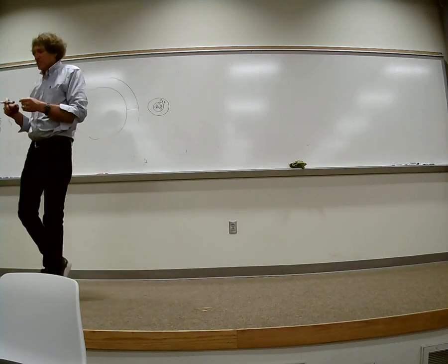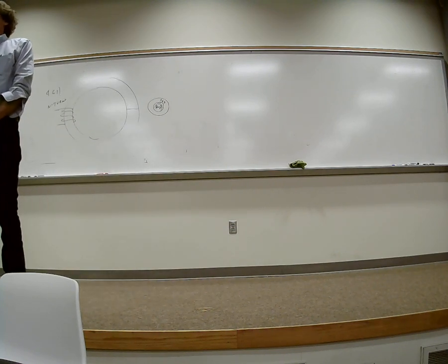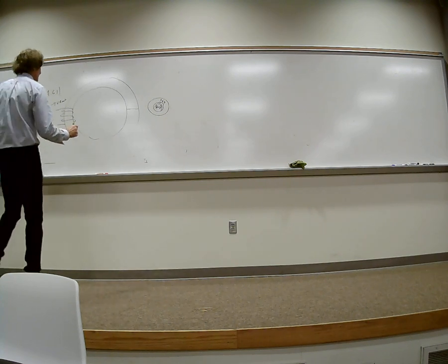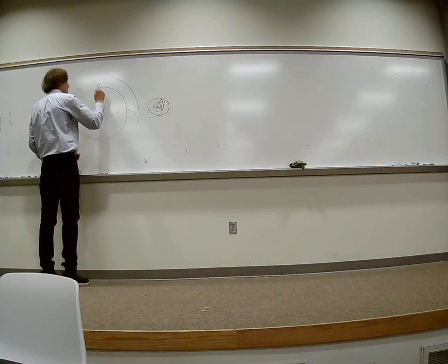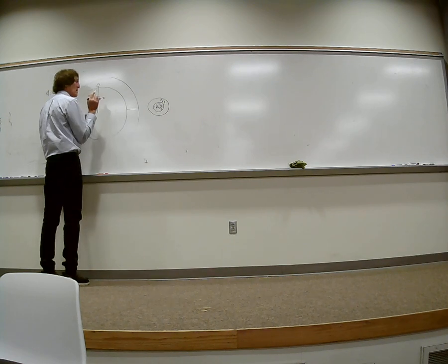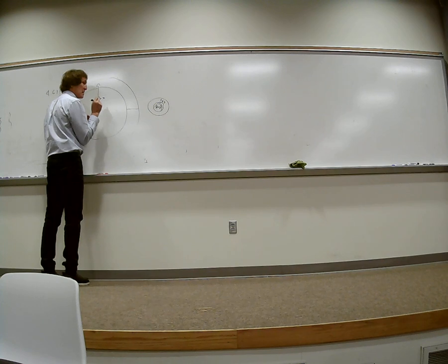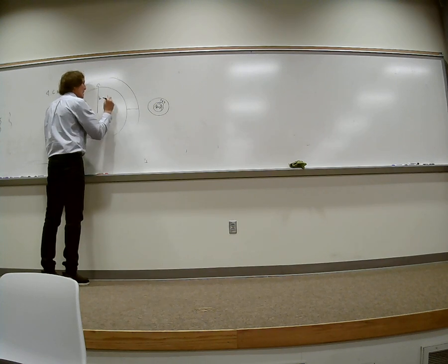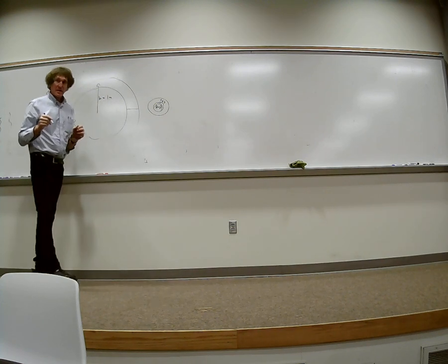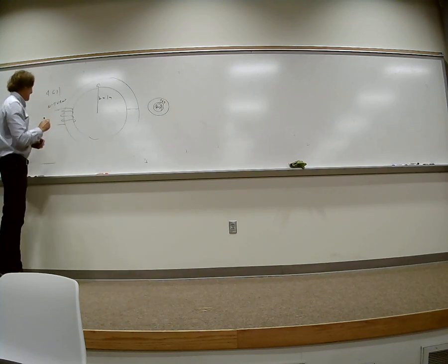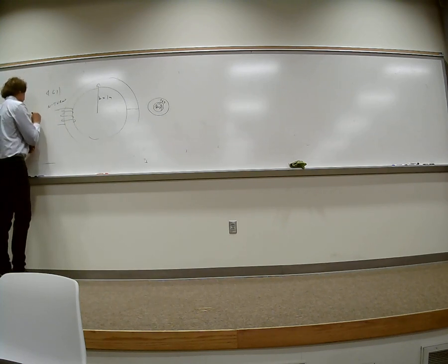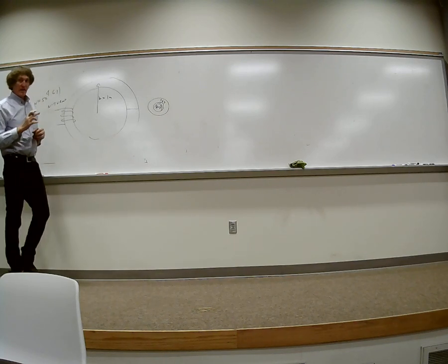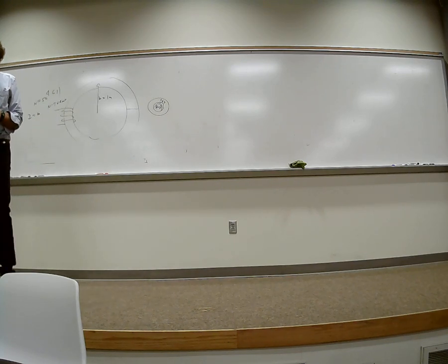And what do they want? The toroid has a 1 meter mean radius, for 20 amps of current driven through 50 loops of wire. Find the magnetic field intensity. What was that radius? The mean radius is 1 meter. And there's 20 amps of current driven through 50 loops of wire, so N equals 50. Find the magnetic field intensity in each material of the toroid.